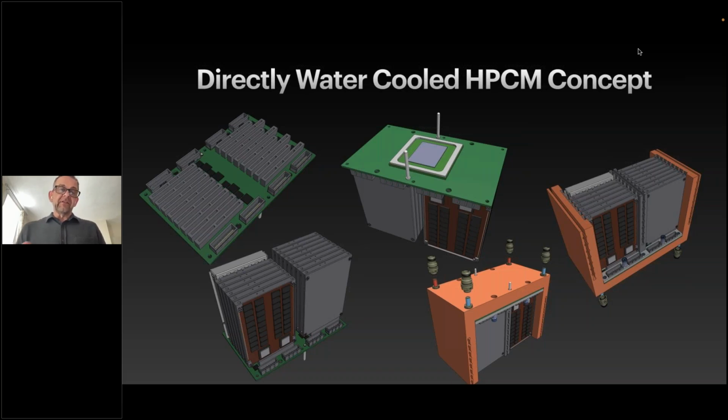Okay, and then the 4 connectors around those are basically standard MCIO connectors in this particular incarnation, which supports PCIe and will support CXL as that comes in, because that's over PCIe. But again, the idea of this module is protocol agnostic, but this is the fundamental mechanical electrical interconnection. So in the bottom left, you can see a bunch of E3.S and a NIC 3.0 populated in the module, with one of them open. That was an OMI one that we designed when I was with OpenCAPI.